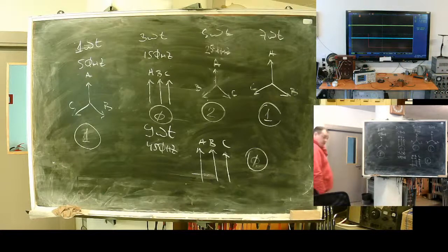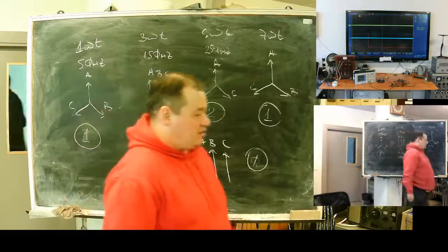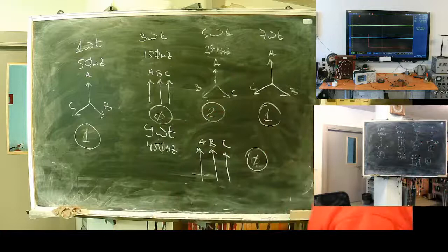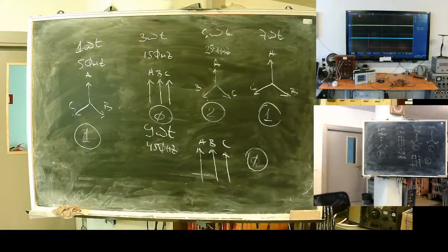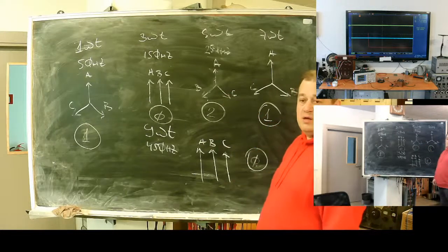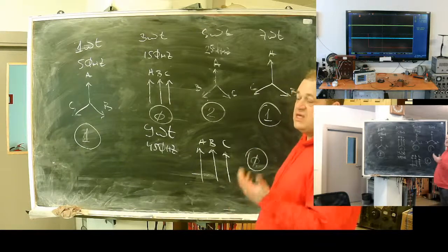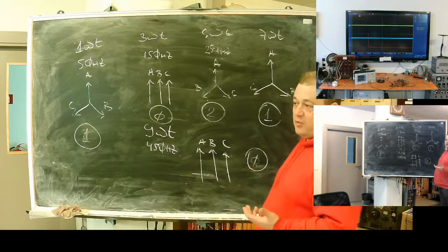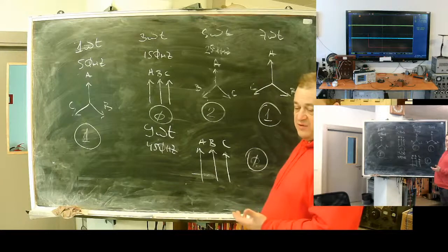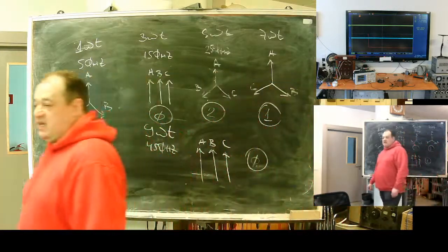Third harmonics, at 9, 15 and so on, behave like a zero sequence. Fifth is similar to a reverse sequence: a symmetrical polyphase, in our case three-phase, system, but with opposite phase sequence.